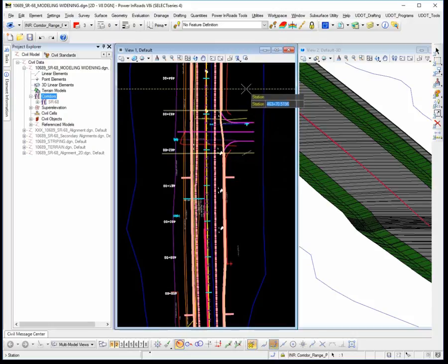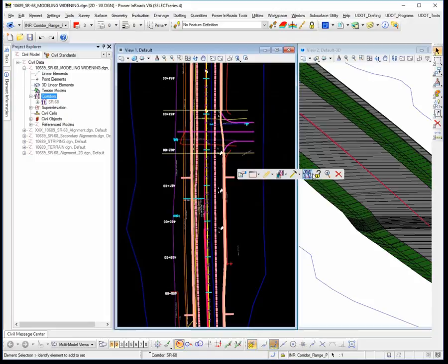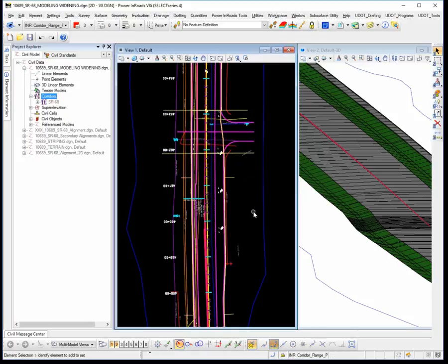Then once I have completed my task, I simply go back to that corridor and turn on the rule. And notice that it doesn't process. It won't pick up those changes until I either manually select to process the corridor or I add another command that forces it to reprocess. Then it'll process that next command plus the 3 that I just did. And so taking advantage of activating that rule or deactivating that rule allows you to make many changes without having to wait for reprocessing.